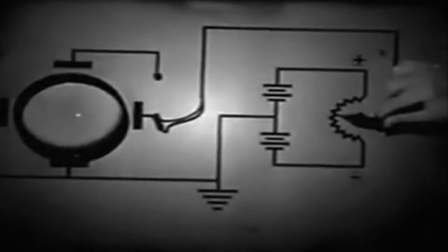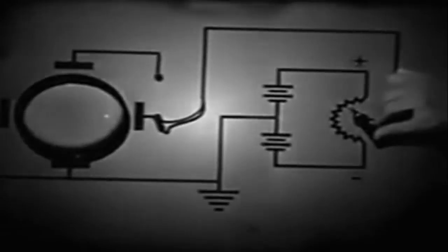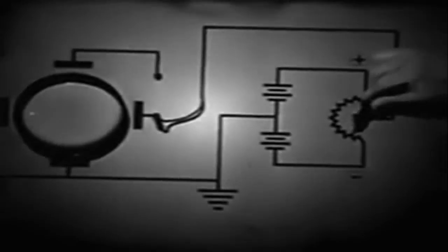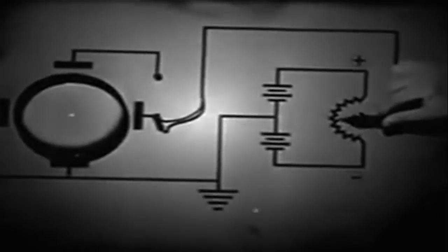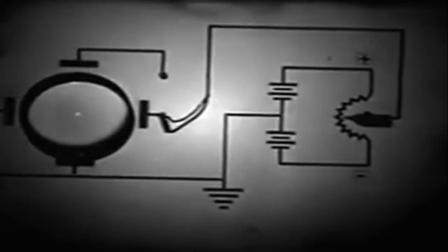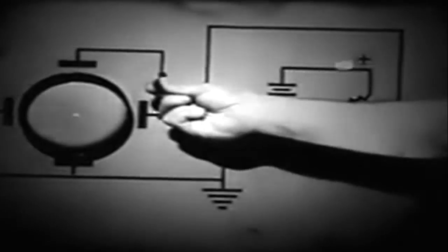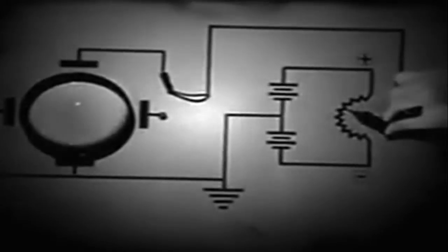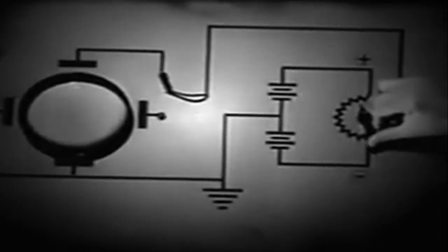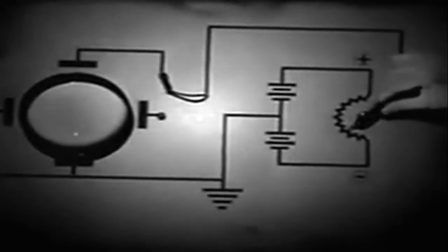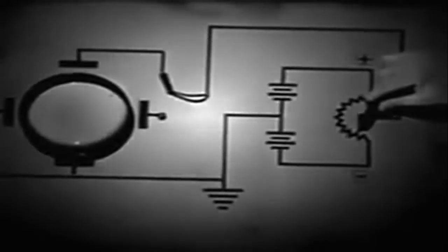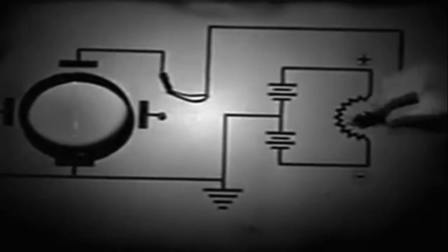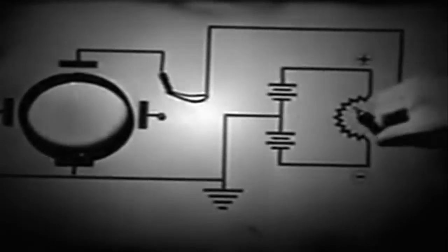Notice that as the voltage is increased positively, the spot is attracted in that direction. If the voltage is increased negatively, the spot is repelled. The same effect can be produced at the upper pin jack. In each case, an increasing positive voltage attracts the spot more and more. An increasing negative voltage pushes the spot farther and farther away. Rapid fluctuations in voltage move the spot correspondingly.